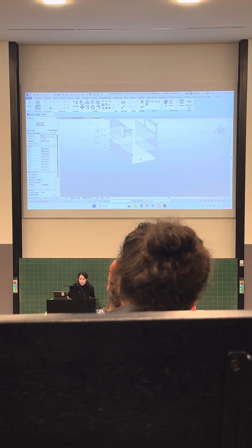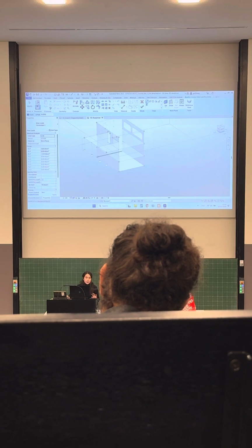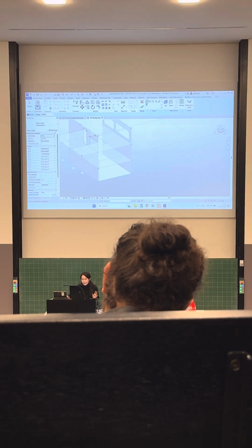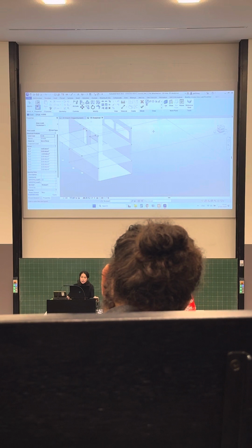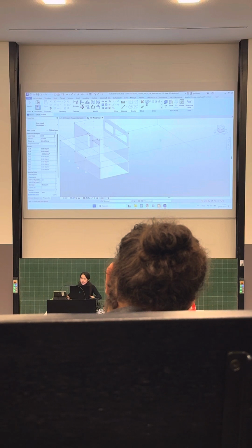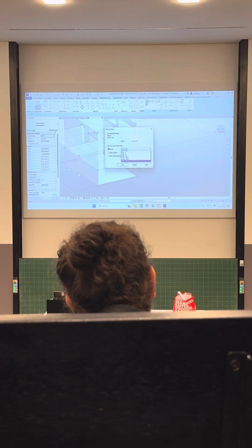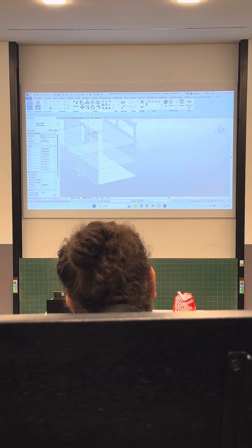usually variable. And if we choose not hosted, a general one, you can see that now I cannot touch it. For some reason, only this lights up. And as I hope you remember from the Revit classes, you need to define a work plane for your load. And after choosing it, you have this create area load boundary. And you need to set the work plane that you're going to work in. And okay, maybe I should repeat the step.